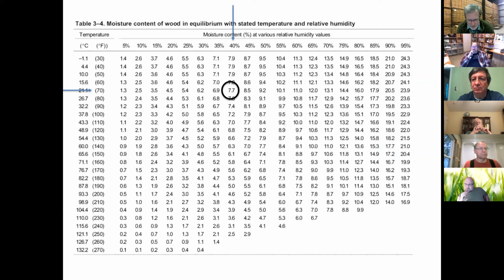Just as an example of how different the East and the West can be, one winter I was out in Denver, Colorado at a door plant, and they had the windows and the doors at the plant open, and the relative humidity outside was 20%. So you can guess by looking at this chart, if we went over to estimate what that would have been, here's 20% relative humidity, right? And it certainly wasn't over 100 degrees Fahrenheit. So that tells you that wood was pretty dry out at that door plant, right? It was less than 5% with 20% relative humidity.